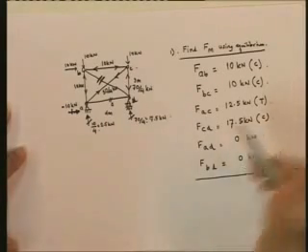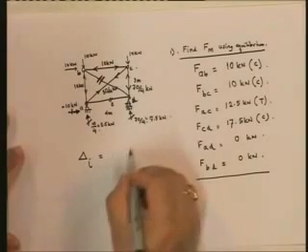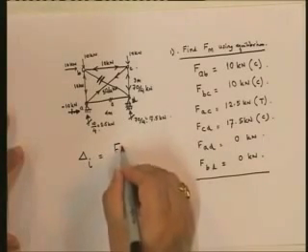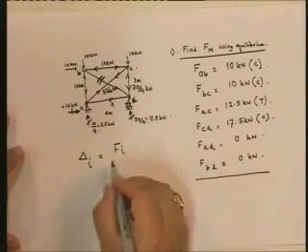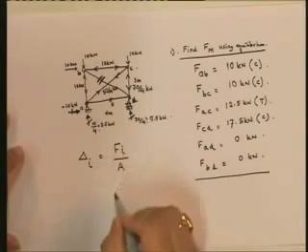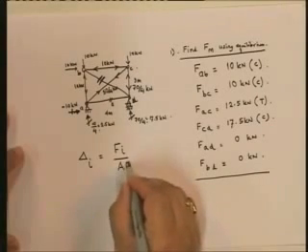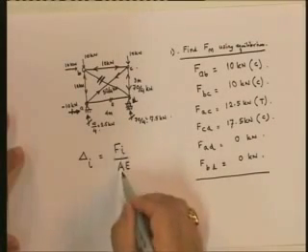The deformation in member i you can find out is going to be equal to Fi, force, divided by A. What does the force divided by A give? The stress. Divided by E. What does that give me? The strain.